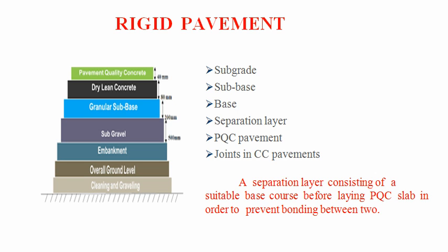The separation layer, consisting of a suitable base course, has to be provided before laying the pavement quality concrete slab in order to prevent bonding between the two.